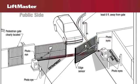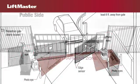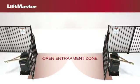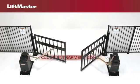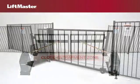Let's look at the entrapment zones related to the open and close cycles of a swing gate, and then talk about the safety devices you need to install to protect those zones. During the open cycle, the most likely points of entrapment are between the gate and any stationary object, such as a wall, column, or the post where the gate is mounted. During the closed cycle, the most likely points of entrapment are posts, a wall, or in dual gate applications, the place where the two gates meet.